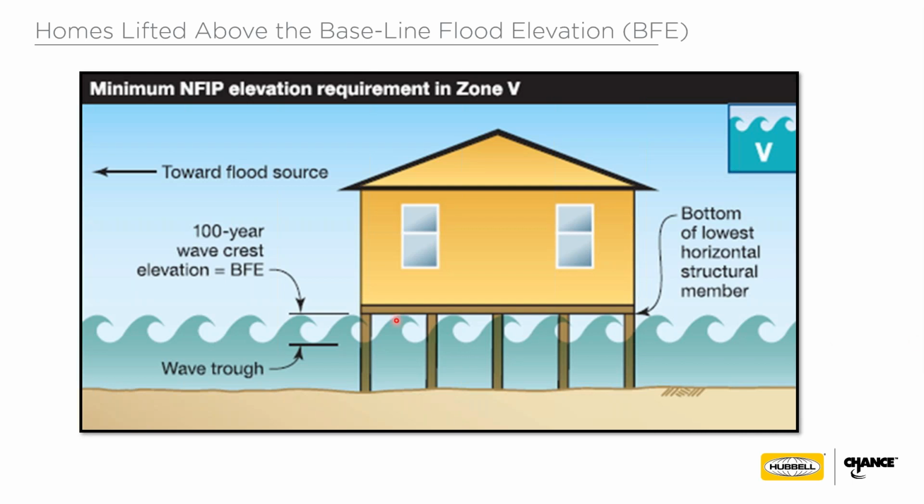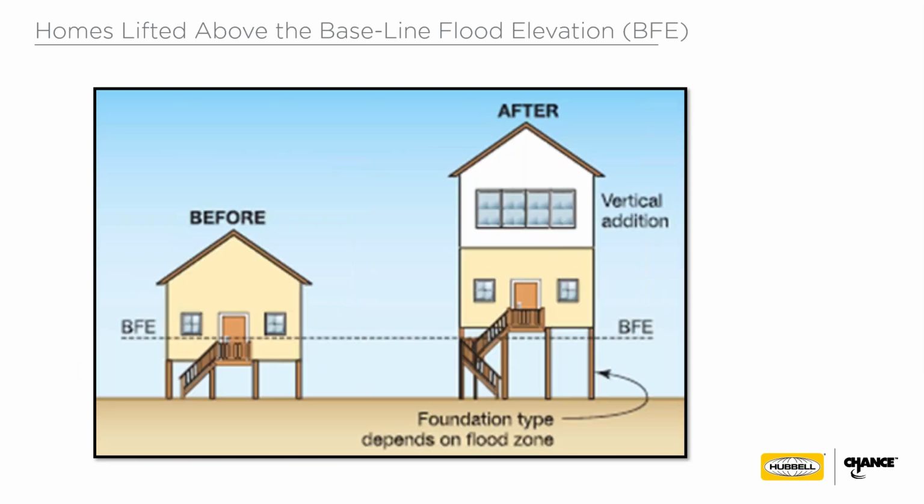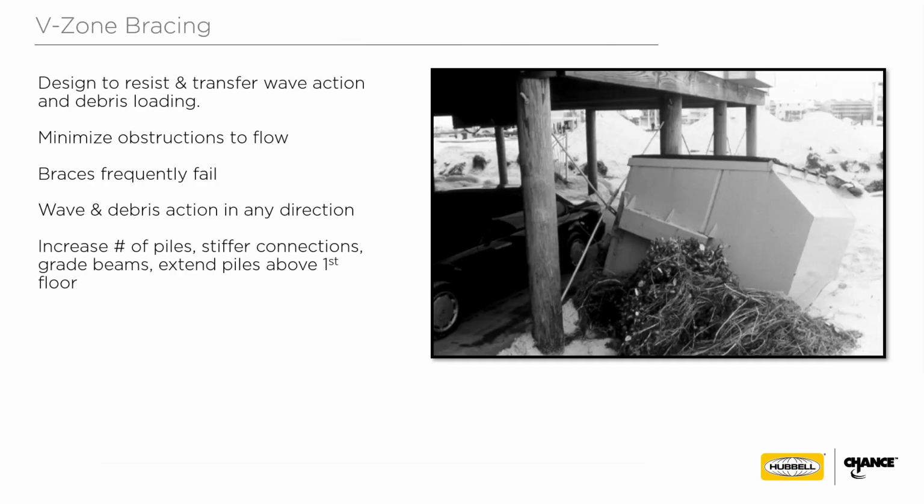But this is the general guideline for V zone requirements when it comes to elevation. So if you're going to be augmenting or adding on, you simply have to get your structures above that BFE, is the main point. When it comes to V zones, it's interesting. FEMA recommends using what's referred to as an open foundation, which, as its name kind of implies, it's open underneath the structure.